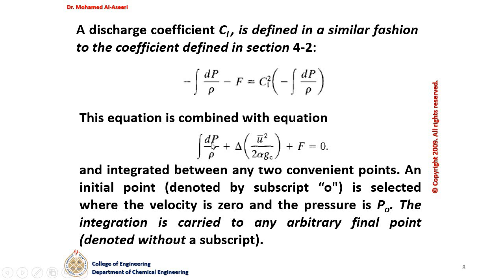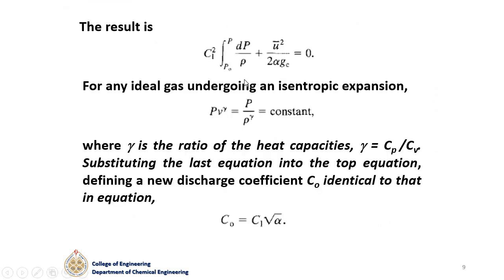Okay, and when we take a dP and integration, of course we are going to say that dP goes from a certain P naught term to a P value. So it changes from P naught to a P value. Doing this now, is it an ideal gas or not? We are going to consider it, for simplicity, as an ideal gas, just to get the trend that we are expecting. And as I said, because it's an isentropic expansion, we could use the generic form that we have from